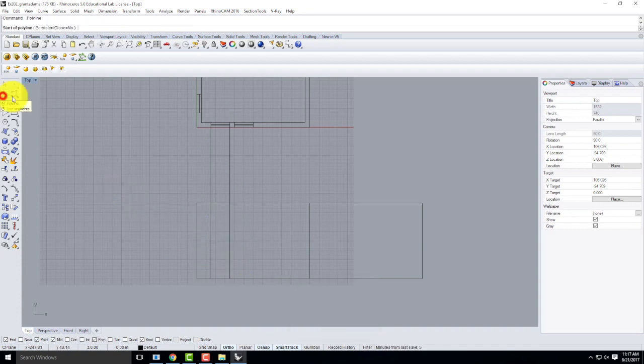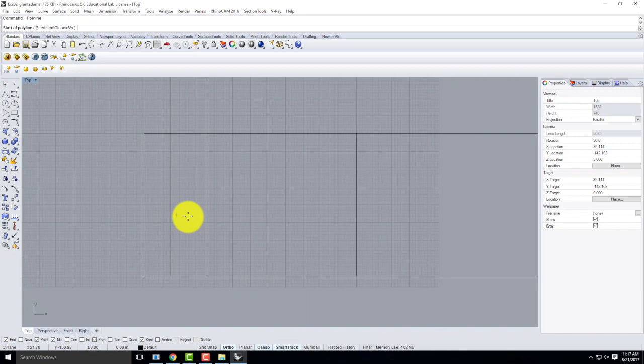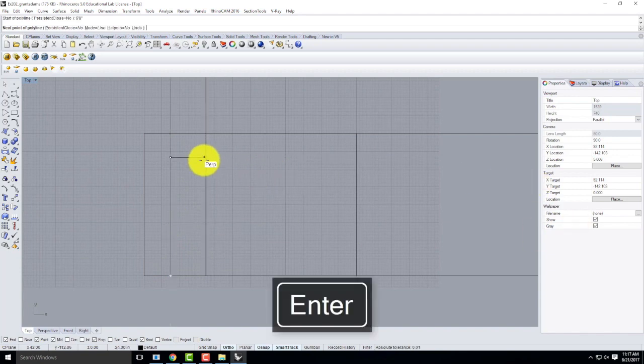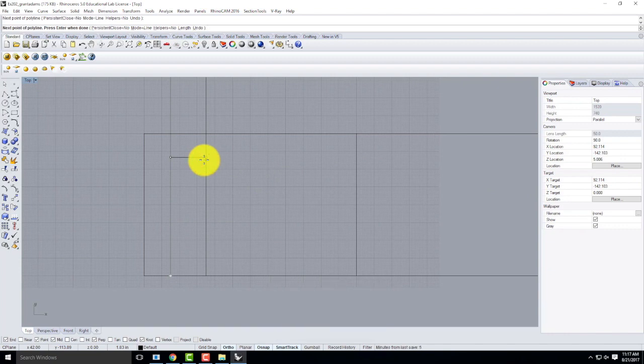going to be. I need to draw the sill of the window and the head of the window. Typically, the head of a window is at 6'8", on an 8-foot ceiling. So I'll type 6 feet 8 inches. And again, if you do something different, it's not the end of the world. This is not a perfect thing. We're learning the skills, not trying to model. I mean, if this was the building we were building, it's awfully boring to begin with. So it's not about that. It's more about the skill set.